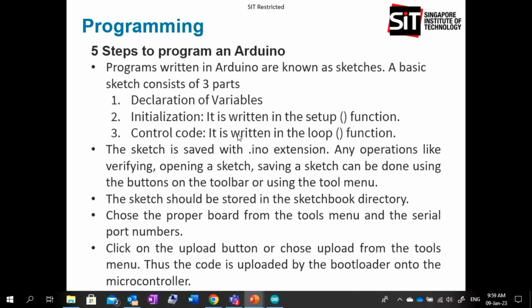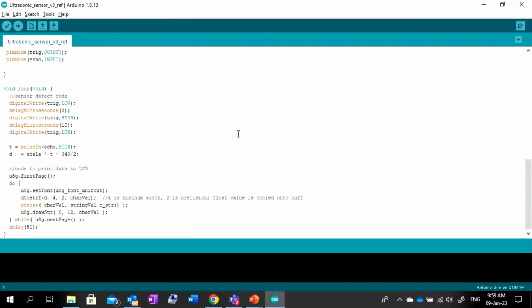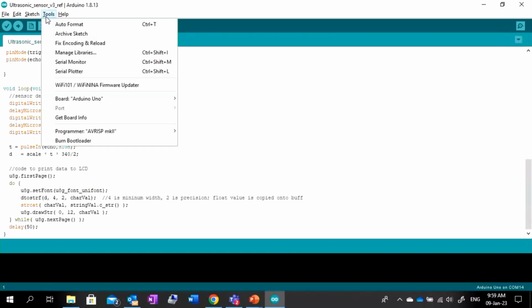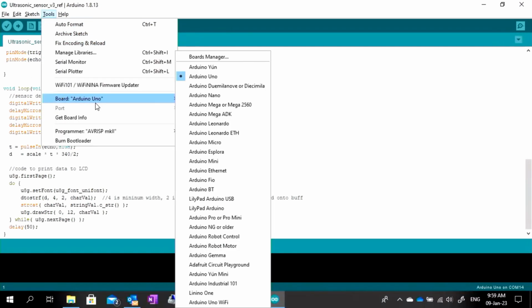Okay, another thing, for this Arduino IDE, it supports many different types of boards. So in case you all have not used, okay, I have used it for things like even the DJI drone. Right? They actually have an Arduino board that you can attach to the top of the drone, and that board can be programmed. So all you need to do, right, is that you need to install the library for the different board, and then when you connect the board, you need to go to Tool, and you need to select.